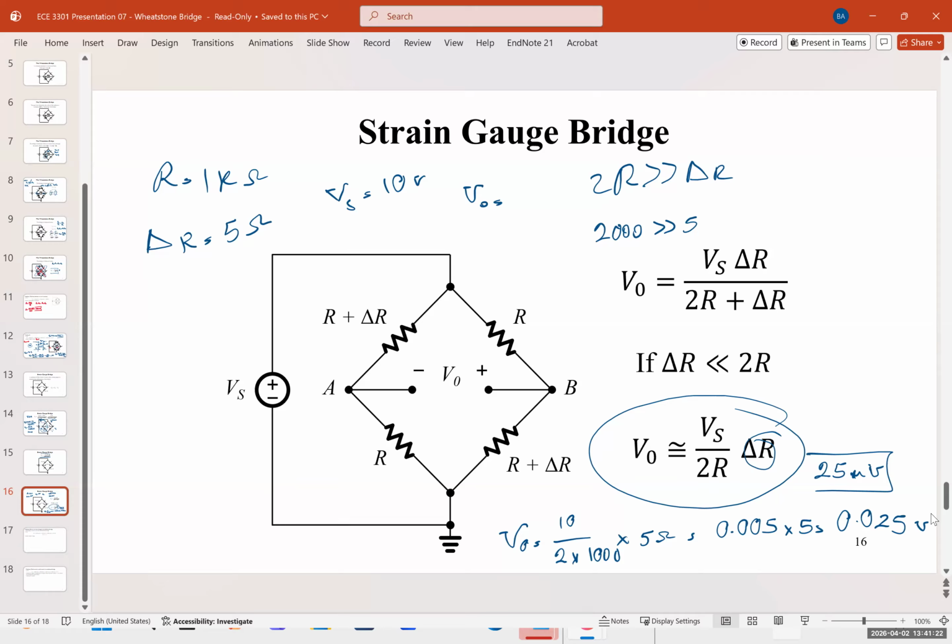that I can replace it with these arms, and we have a lab that's specifically dedicated to this. We're going to have it next week, where we're going to replace one of the arms with a strain gauge and then with a photoresistor. I would show you, you can use your phone's flashlight, put it on the photoresistor, this delta R would change and the output voltage would change. And you can code your Arduino and say if the voltage is above a certain threshold, you're going to turn off the light, and if it's below that, you're going to turn on the light.